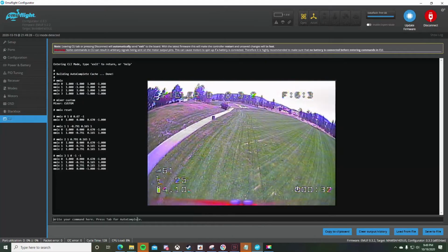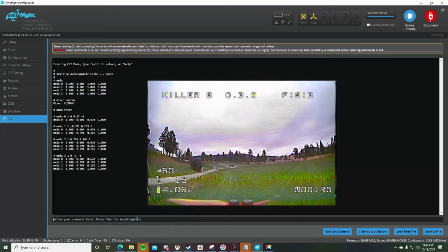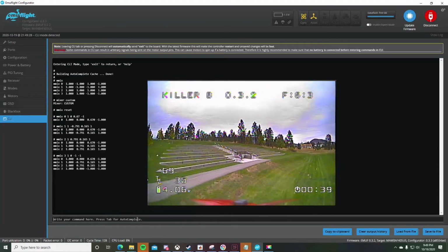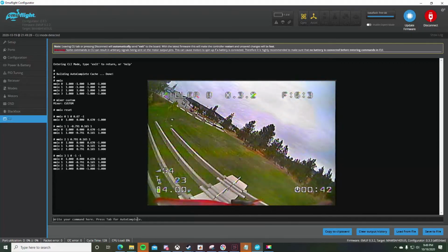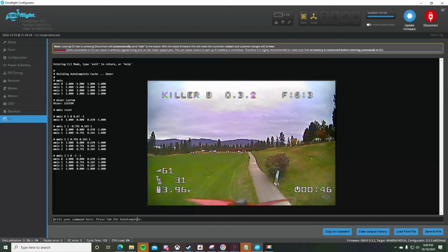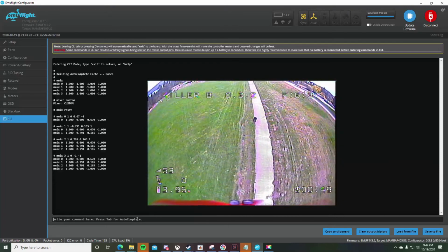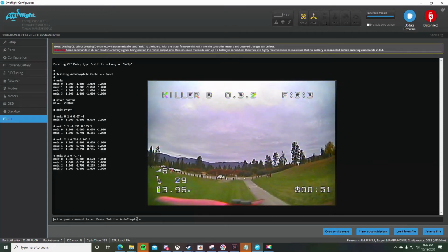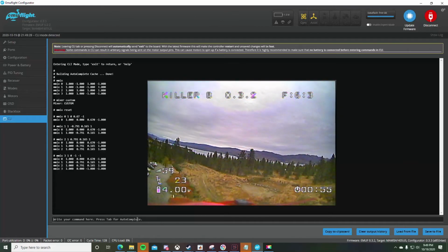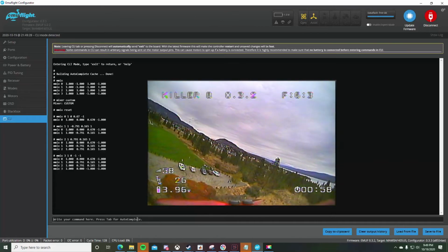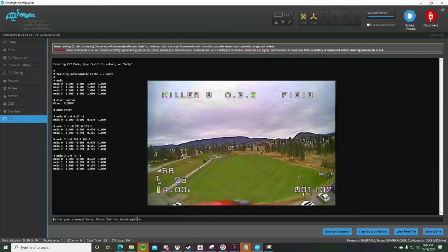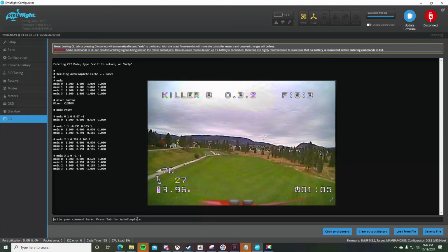The moment of truth, I went to a field up by my house and tried a snap roll. A couple flips. Instantly, the drone was locked in, no more death spirals. Anything regarding that desync or PIDs wasn't actually the case, and I had a relatively normal feeling quad. Obviously, not all things are fixed. There's always better tuning you can do, but I hope this helps anyone who has any similar issues.